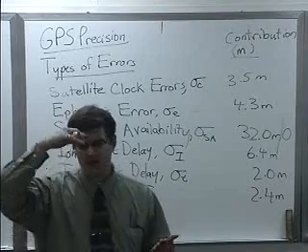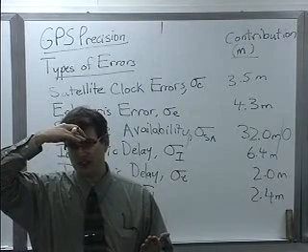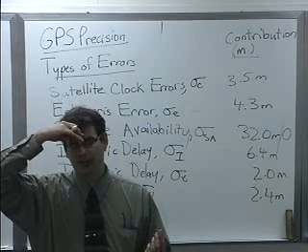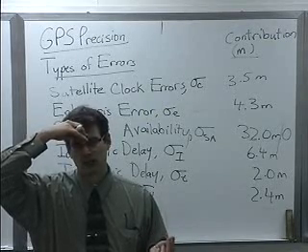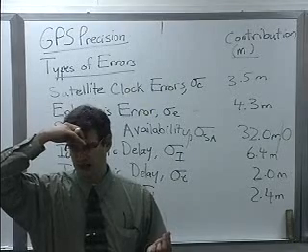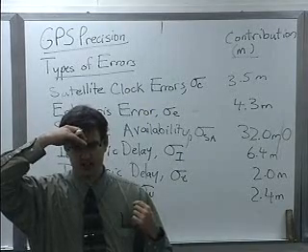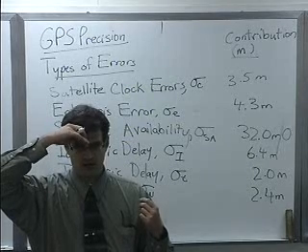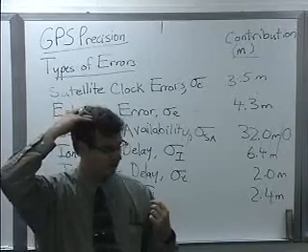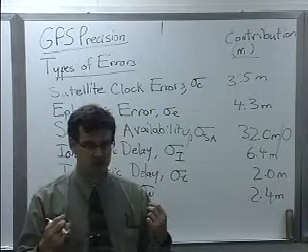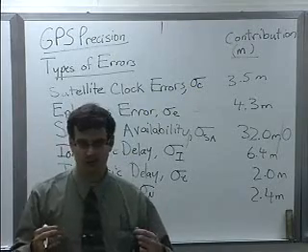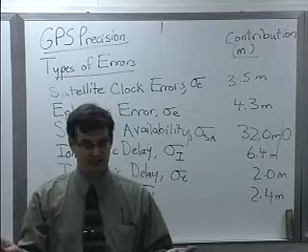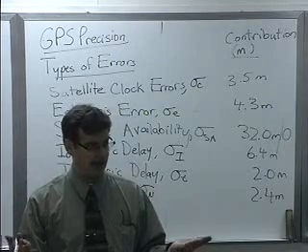But if you think about it, the waveform in GPS is chipping at about 1 megachip per second, which means a chip lasts about 1 microsecond. Now, how far does light travel in 1 microsecond? About 300 meters. Very good. So it's 1,000 feet roughly, like the English system. 300 meters, 1,000 feet. That's a long way.